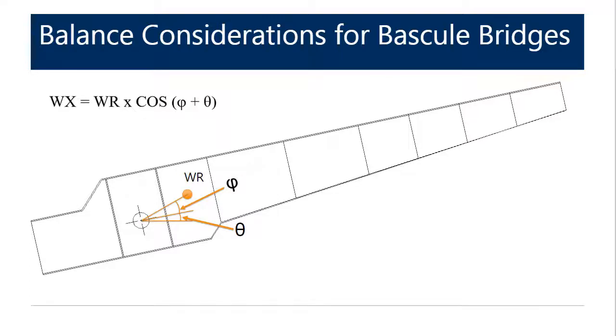Calculations can be performed to determine what weight change would be required to shift that angular location of the center of gravity to have a favorable imbalance, but the ability to implement and achieve that desired balance condition is limited to the physical constraints of where you can put your ballast installation or your weight installation, and where it can be added on the structure.